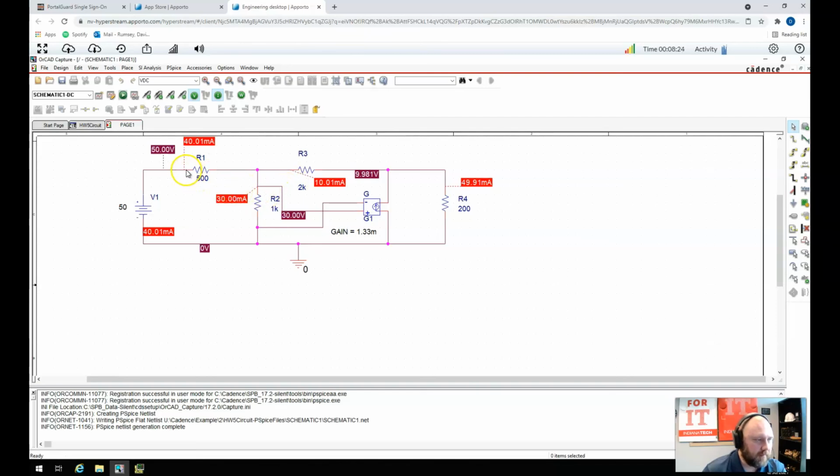And again, notice how it's put right on the edge of this component here, because again, you have to talk about current flowing through a component. And then you can even turn W on, which is then talking about the amount of power. Now, I will point one thing out here. Notice how this says -2 watts, and these are positive numbers. -2 is meaning that power is being taken away from something. So negative means power is taking away from something, which makes sense. The battery is powering the circuit.